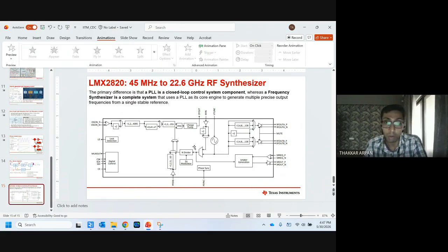Now, just to give you an idea, this one's frequency accuracy, across temperature and all, can be as bad as 5%. So if you want a frequency of 11 gigahertz, I can end up giving you a frequency of around 10.75 gigahertz or something, right? That much off I can be. So we want at least the frequency exactly the same, right?